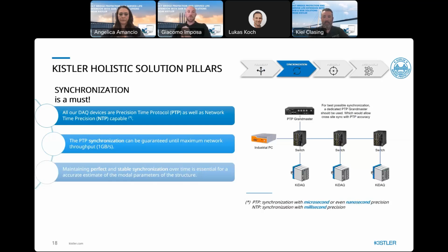Another important feature is synchronization, because imagine that you are taking a lot of pictures of the bridge at different times, but also from different parameters. If you don't keep synchronization, as an important value, with different types of protocol, we provide the Precision Time Protocol as well as the Network Time Protocol. In this case, the time lapse is about microseconds, even milliseconds. If you don't have this type of requirement, you are not able to match all this information in processing, and you cannot have a really robust overview of your bridge.